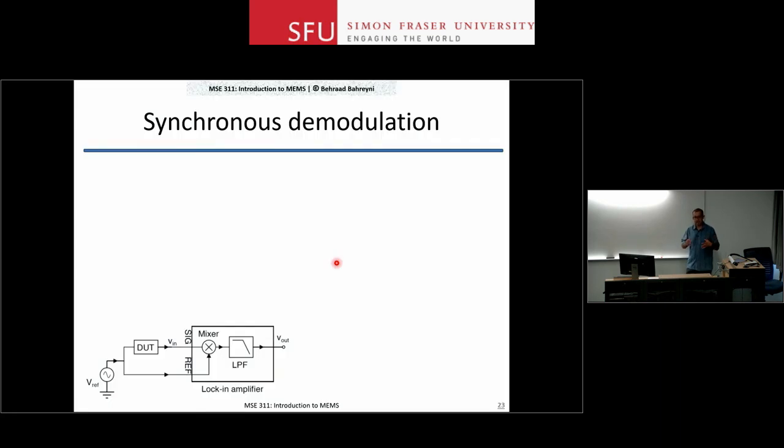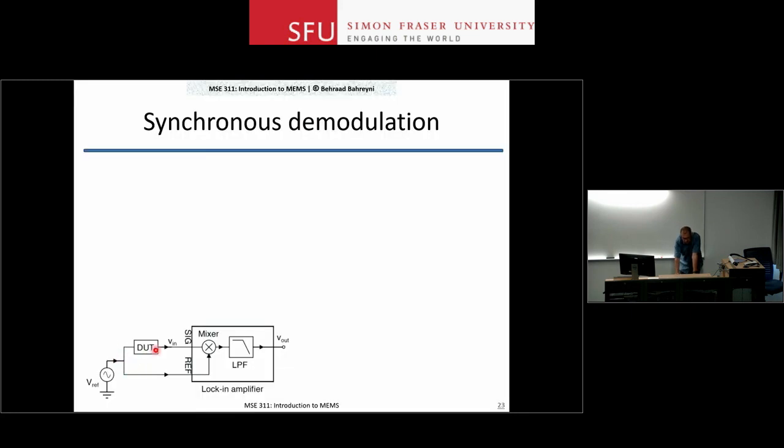So this is the setup that I use. This is how I deal with this challenge. What I do is that I go and take my device, I feed it with a reference signal, and I measure the signal at the output of it. At this end, the output of this device under test, well, it's a linear device, will have an amplitude and phase difference depending on what I feed into this signal.